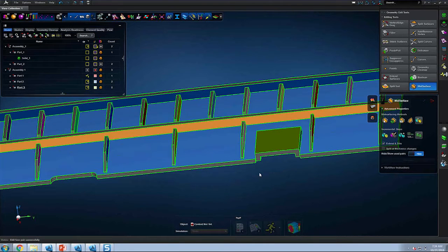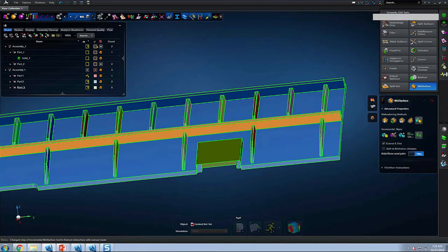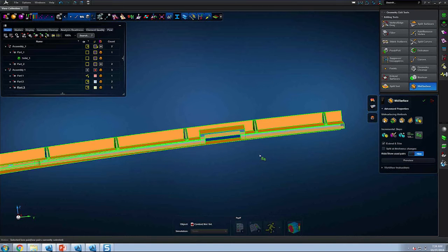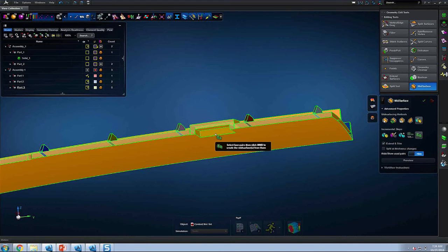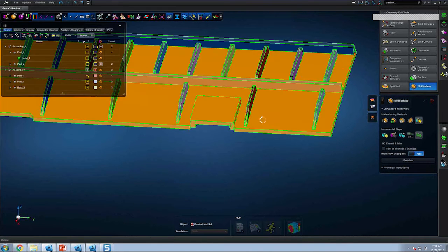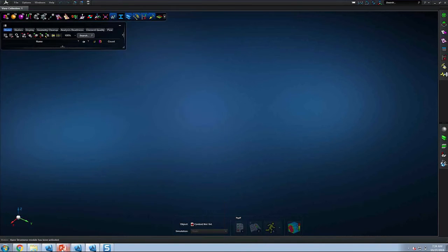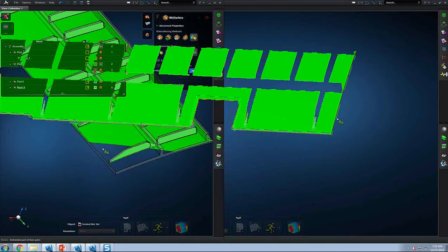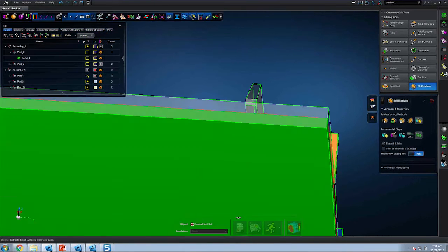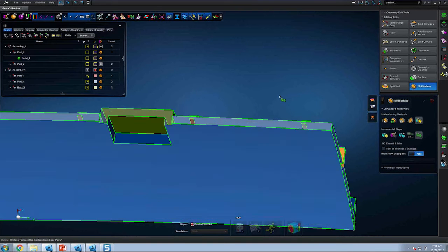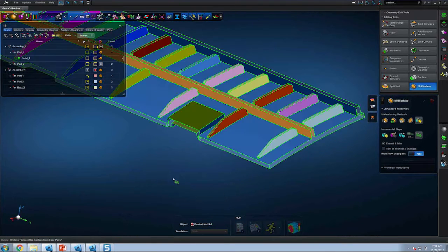Now if I go ahead and extract the midsurface geometry for these pairs, you'll find out that I no longer have this missing piece in the corner like I did a moment ago. So again, we're trying to fix this piece of the geometry that you see here on the screen. And here's the final result after we modify the automatic extraction method. Now again, we're getting closer and closer.